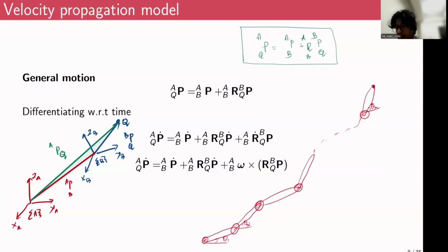You can maybe express that in task space coordinates, maybe x dot, y dot, z dot. If the robot is a spatial robot, you will have to express the velocities in linear velocities x, y, z, and also the angular velocities, maybe theta dot, psi dot, phi dot.